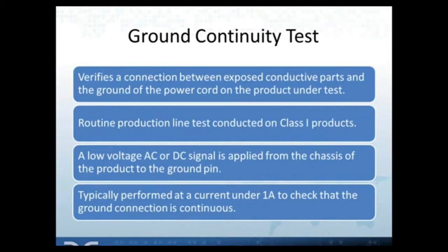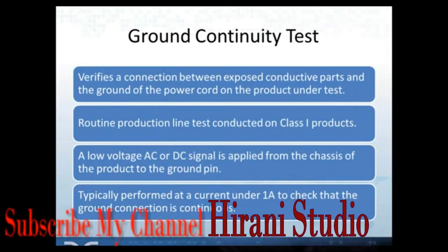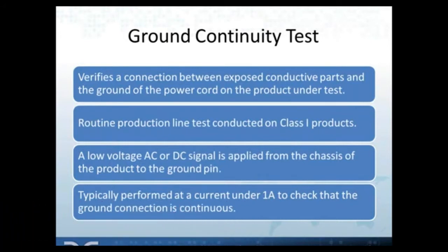Now, a ground continuity test is normally required as a 100% production line test on electrical equipment to verify that there's continuity in the ground circuit of the device.